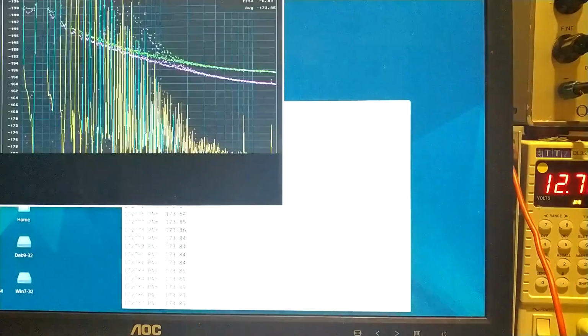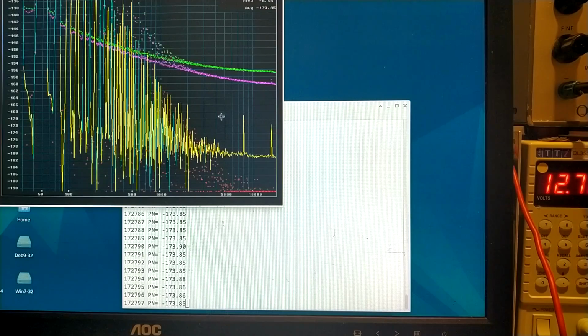At the same time, I have been running at high speed, and here you can see that this transient has not been allowed to enter the measurement. So it shows that the noise floor is at minus 180 dBc per Hertz, and I can see it should be at the 200 Hertz or so, where I saw minus 140 something. But here I can read minus 174 or something like that, between all the overtones of the audio frequency.